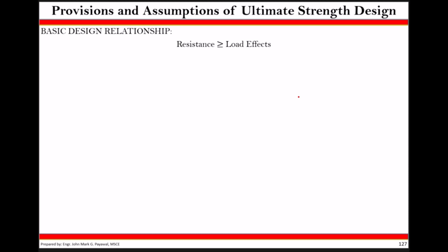It's very simple that your resistance should always be at least equal or greater than your load effects. Here, your load effects would be your demand. Your load effects is caused by your loads or load combinations, in particular for USD. What does it mean? If you have dead load, live load or earthquake loads, those loads would induce effects. And those effects would be termed as the demand of our situation that needs to be resisted or needs of resistance.